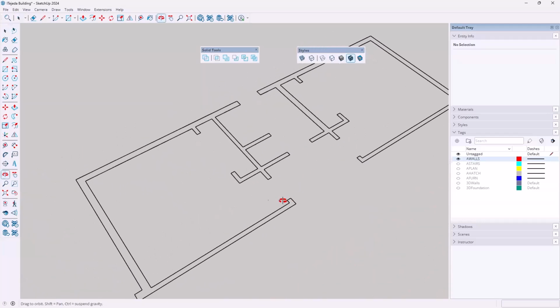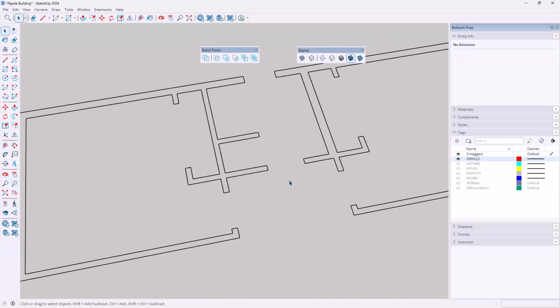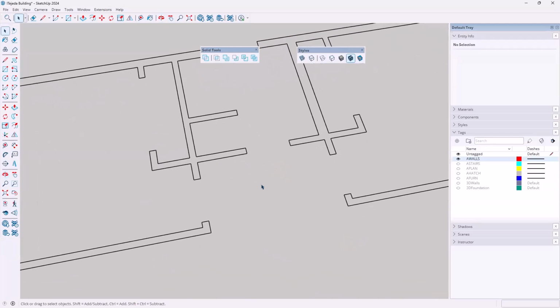So here's what I'm going to do. I know that they're aligned to one another. So I'm going to draw a rectangle from this endpoint over to this endpoint. Now, the height of my doors, they are 6'8" plus 2 inches for the frame is 6'10".